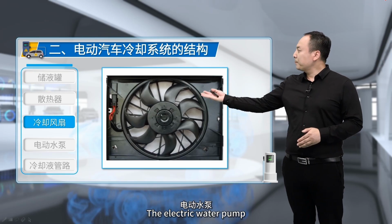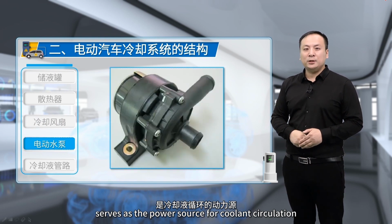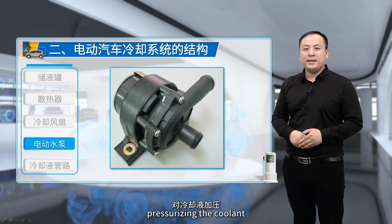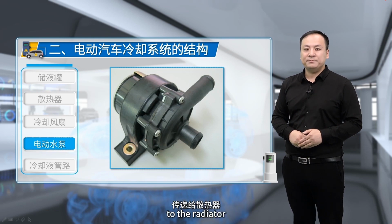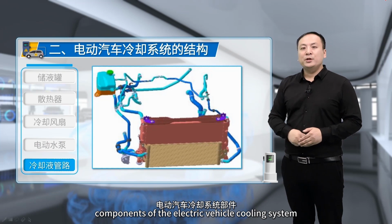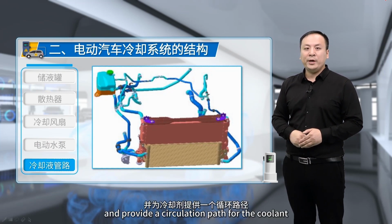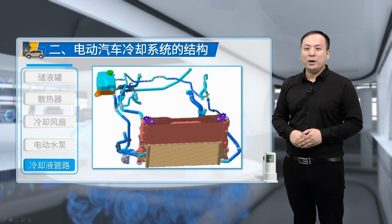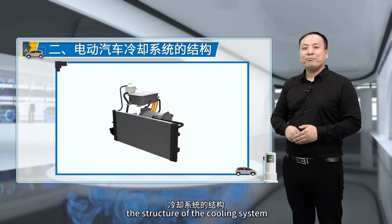The electric water pump serves as the power source for coolant circulation, pressurizing the coolant to circulate in the cooling system, and transfers the heat generated by the drive motor system to the radiator. The coolant pipes connect various components of the electric vehicle cooling system and provide a circulation path for the coolant. Next, let's watch a video about the structure of the cooling system.